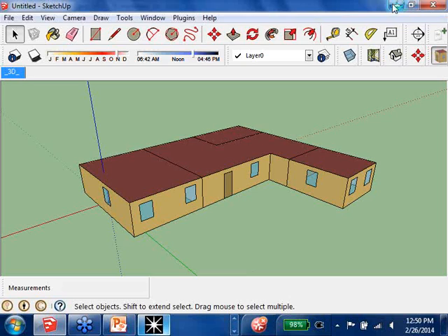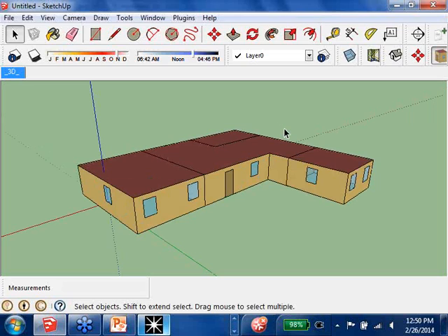So Lauren, how do you apply surface reflectances in SketchUp with the DXF route versus here in the OpenStudio GBXML stream? Well, okay, so this is something maybe if Alan has any additions to whatever I'm saying, let me know. But we've always just applied material names, and then once we're within text mode, we end up editing the materials file and adding the reflectances there.